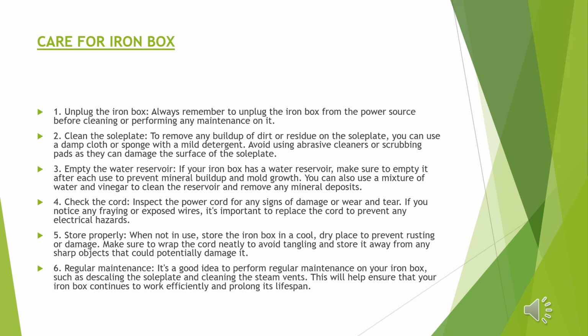Check on the cord. Inspect the power cord for any signs of damage or wear and tear. If you notice any fraying or exposed wires, it's important to replace the cord to prevent any electrical hazards.